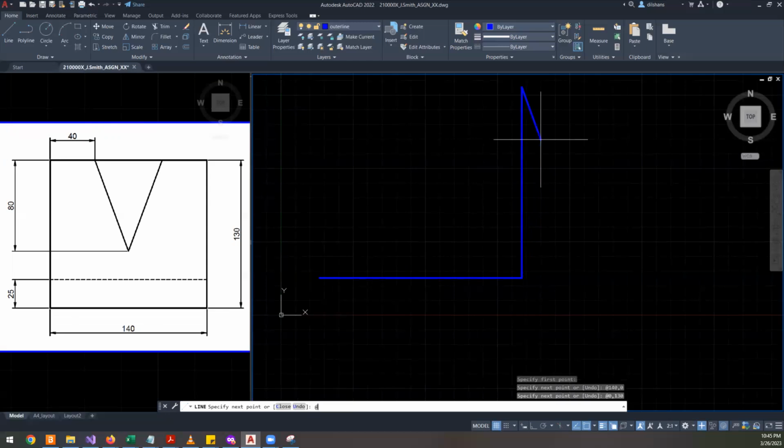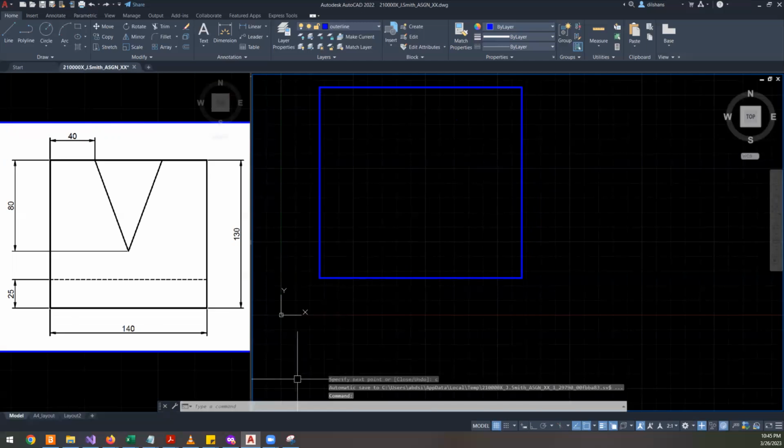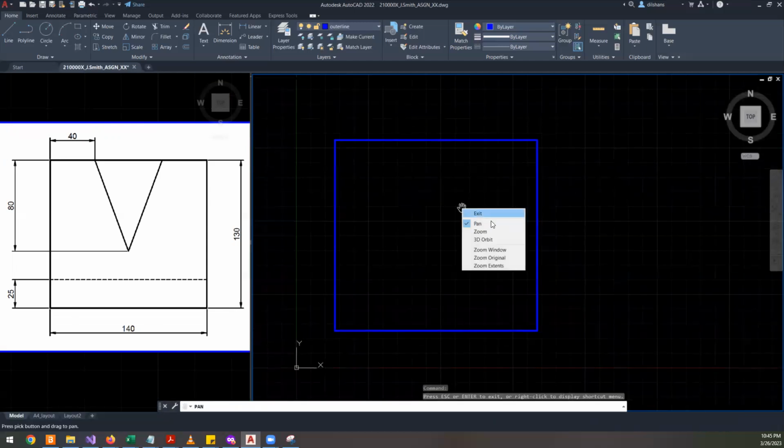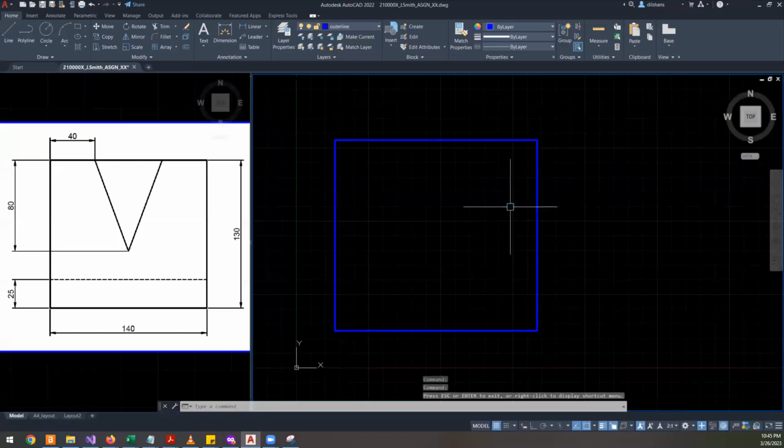And for the next one, @-140,0, don't forget that. And then I can simply close it. So what I did was I typed C and enter, which happened really fast. So if you rewind the video, you will see it. Okay, now I have this one.